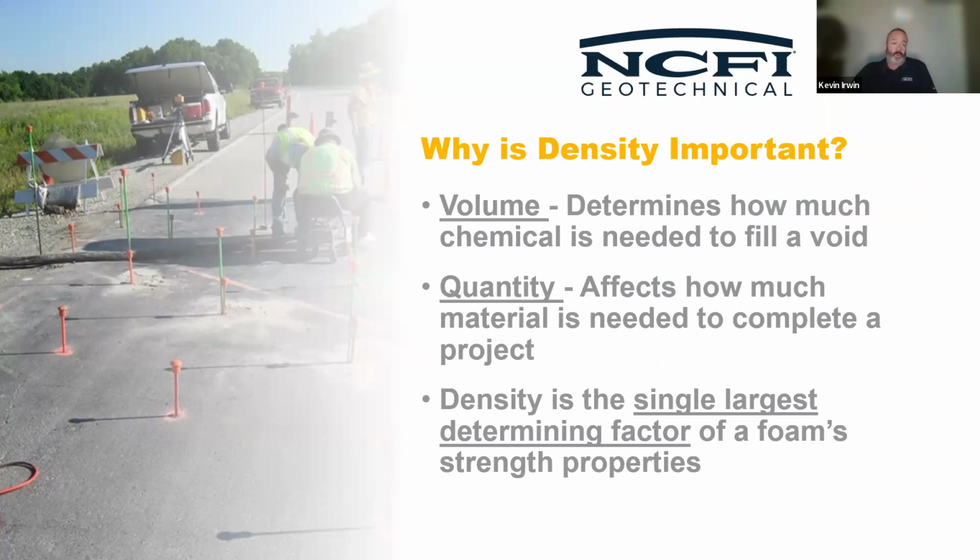So why is density important? Well, it determines how much chemical is needed to fill a void. If I've got a large void to fill, of course at NCFI we do have large void fill foams, and that density of the foam is going to directly relate to, in a pure void, how much foam we're going to use.